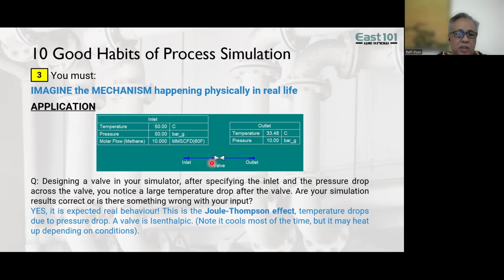Yeah. So this is the Joule-Thomson effect. What I've described is just the Joule-Thomson effect. We learned in thermo that when you put something across a valve and you have an expansion, you get a temperature drop. So it's a good idea to understand why there would be a temperature drop and relate that to the intermolecular forces, your attractive forces. That helps me understand and appreciate things more, and I would assume for most other engineers, that would be the case.